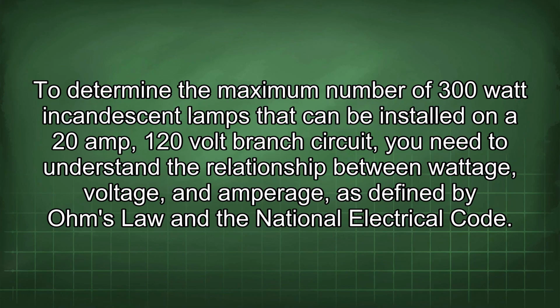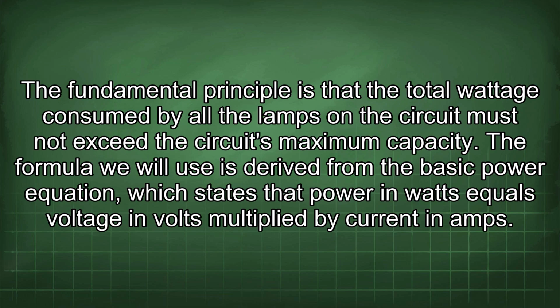To determine the maximum number of 300-watt incandescent lamps that can be installed on a 20-amp, 120-volt branch circuit, you need to understand the relationship between wattage, voltage, and amperage, as defined by Ohm's law and the National Electrical Code. The fundamental principle is that the total wattage consumed by all the lamps on the circuit must not exceed the circuit's maximum capacity. The formula we will use is derived from the basic power equation, which states that power in